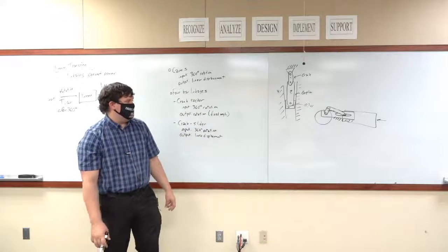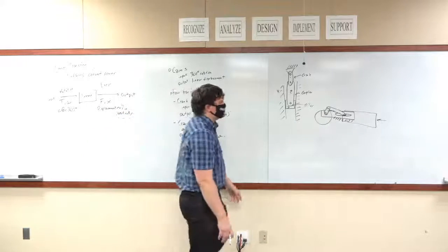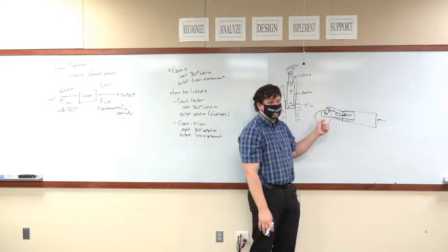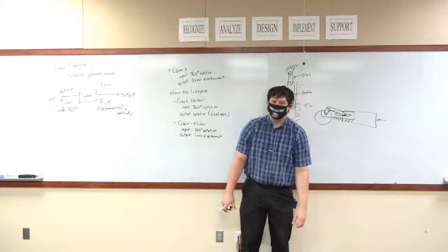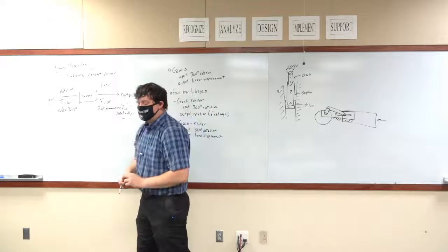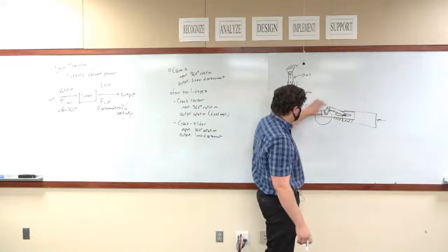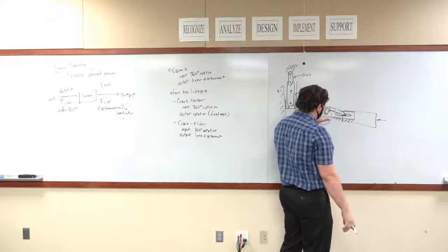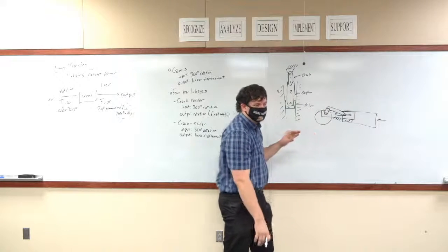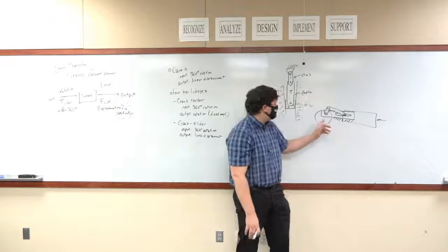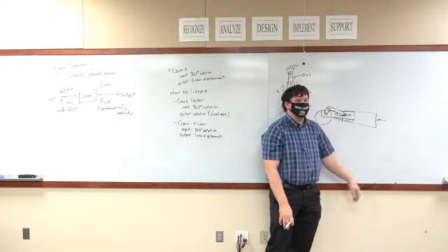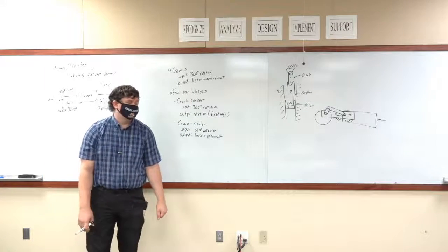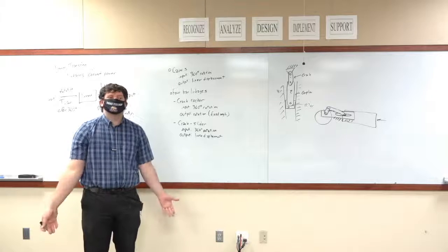Okay? You have your maximum transmission backward, so any resistance on this side, it's going to be really difficult for this mechanism to overcome that. Hopefully you don't burn out your motor. You'd have to get a really powerful motor that can produce the torque capable of generating a force in this mechanism, so inputting torque, outputting force, linear displacement, that is capable of continuing to move even if your object hits something right there, like if it's climbing a stair or something. Okay? It's all about power transmission.